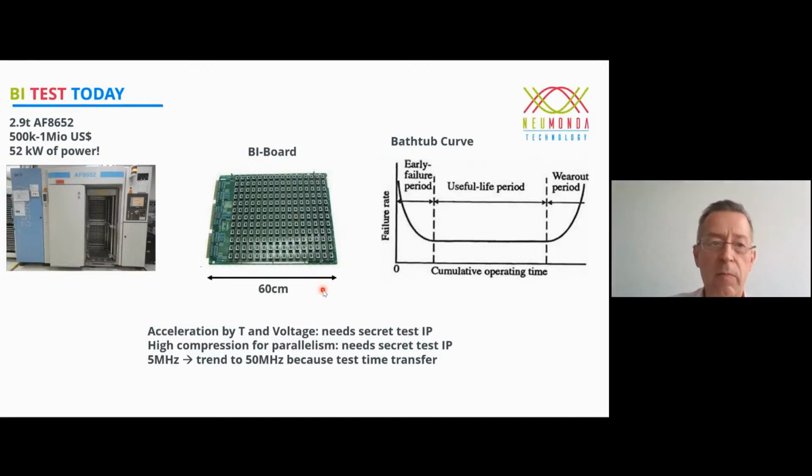How can you simulate aging of your part, 3 months or 6 months of lifetime, with a test that lasts only typically 4 to 10 hours? You need acceleration. This acceleration of semiconductors you achieve by temperature and voltage. So you operate it at much higher temperature than usual. So 125 degrees. No customer is operating the DRAM at 125 degrees.